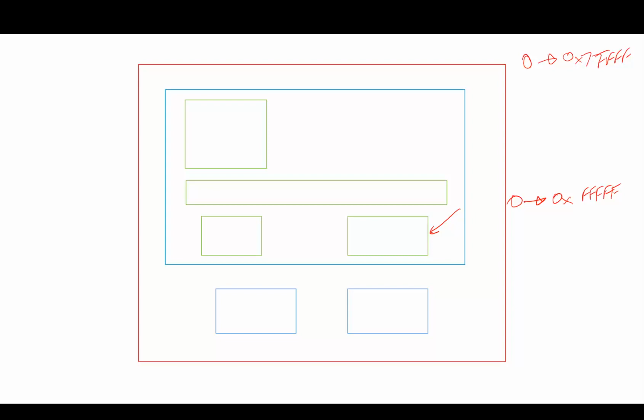Okay, so what you need to do now is you just change the top level module. The only changes you make are in the top level module. You are creating the part 3 top level module by putting together the other 2 parts. So in your top level module, you create an instantiation of the peripheral, and then you create an instantiation of the SRAM controller.